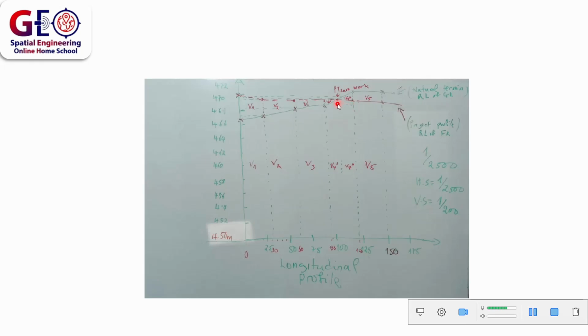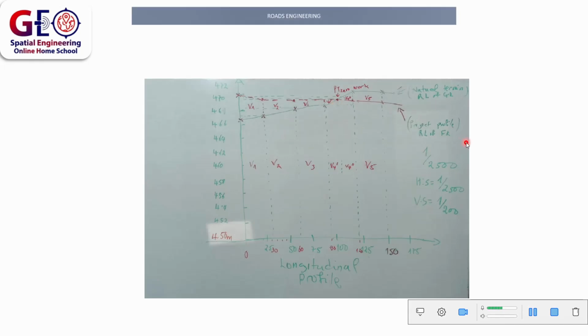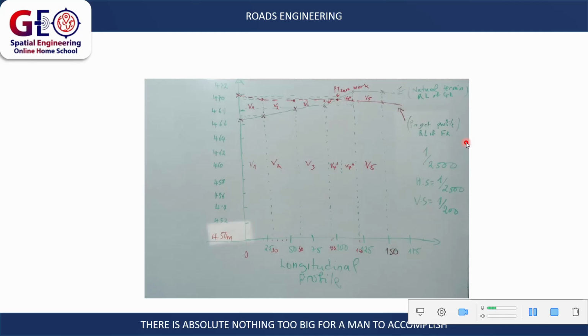Then when we are going towards chainage 120, we notice that there is an intersection between chainage 90 and chainage 120. That intersection is actually the point of zero work. That means at this section of the road, there won't be any cutting or any filling. So we have to calculate the distance that we have to move from chainage 90 to arrive at the point of zero work.